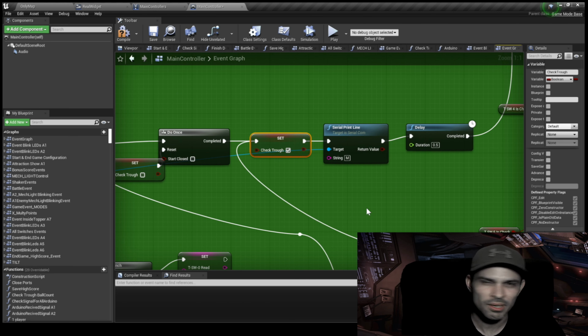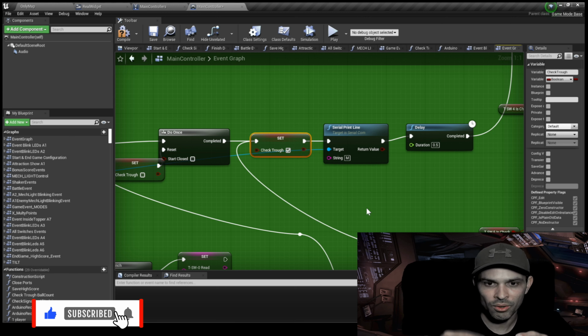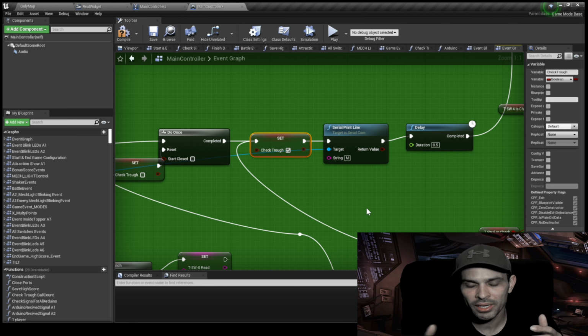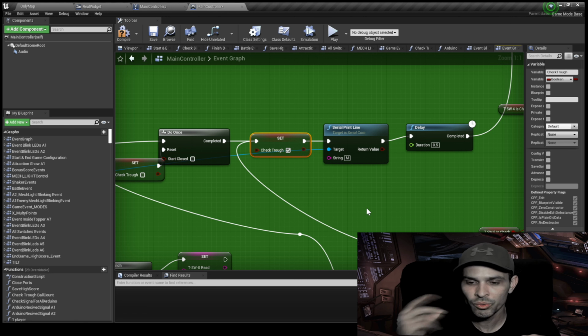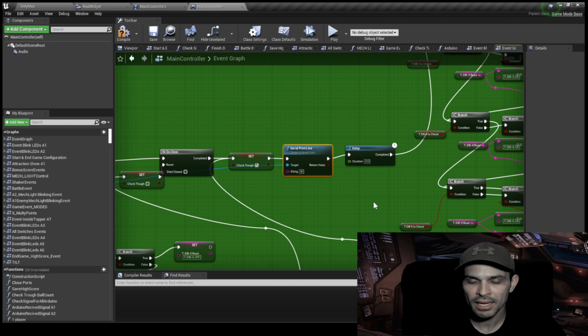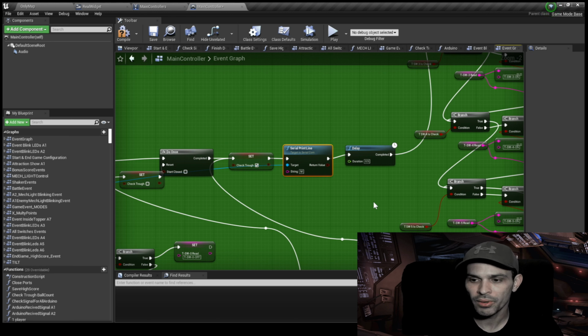Something happened in between that reading, maybe Arduino got so busy with so many calls that it just says, no, I got a faulty reading, give me another reading because I didn't get this one, so do it again. That basically prevents any false reading in my machine, and that's the way I coded this.